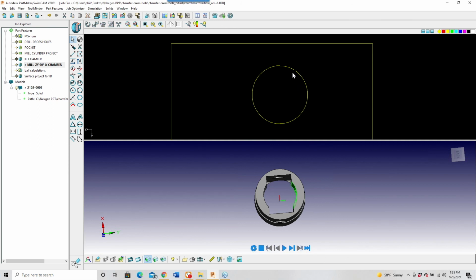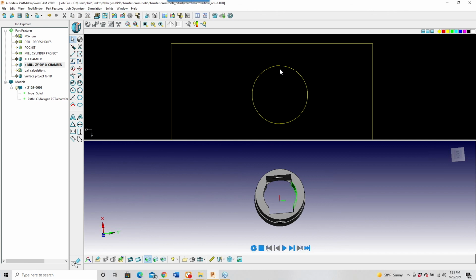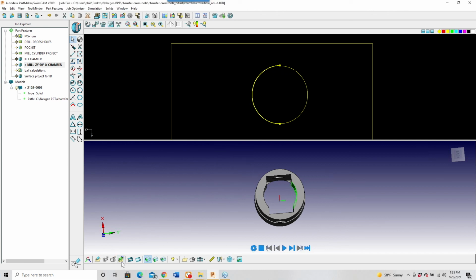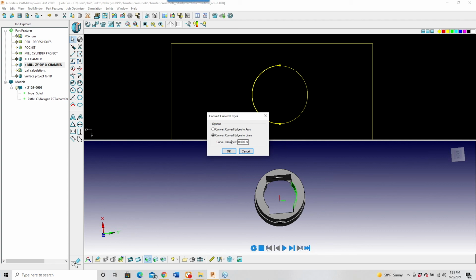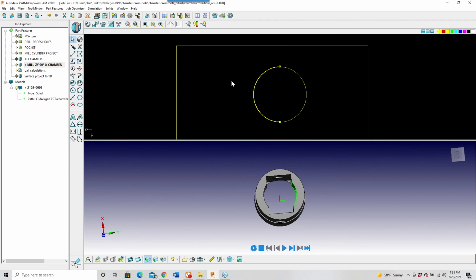In many cases, the arc's going to be broken anyways. It won't be a whole arc because it's got to fit. And that's what the arc function here does. We're fitting the arcs here. And the fit tolerance is this value right here. So again, the more accurate the tolerance that we translate, the better the fit. But in many cases, that could create more code at your machine. One of the key features in surfacing on any Swiss machine is how much memory you have on it.